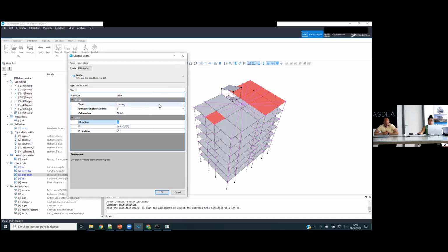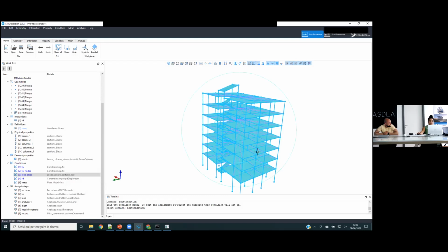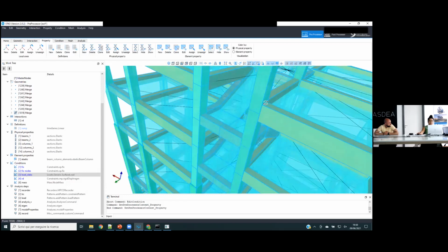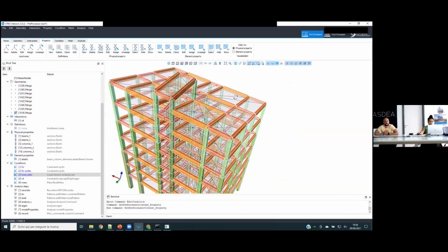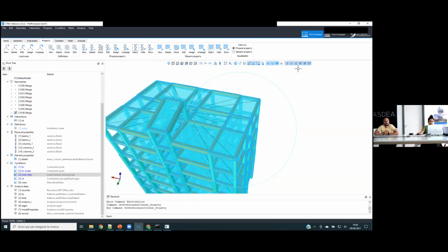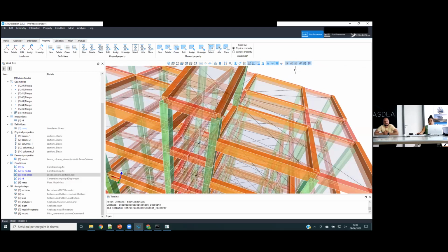But also, the reason I chose one-way in this case is because some of my slabs, you can see it from the property assignments, do not have elements in both of the directions. For example, the ramp here only has elements on one side. So for me, it has to be one-way, otherwise it will not compute. Yeah, but if you have a face with all the boundary edges that have a beam property assigned, then you can use the two-way. Okay. Now that's my first question.